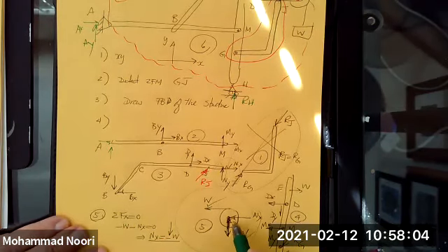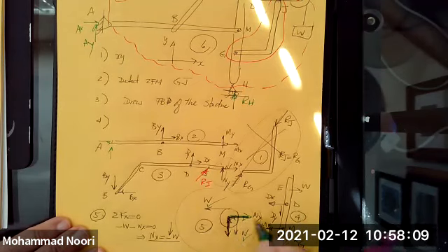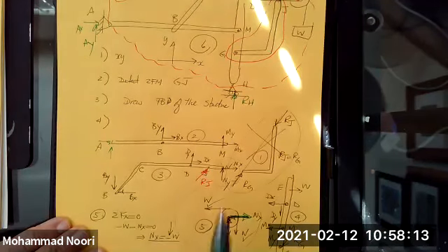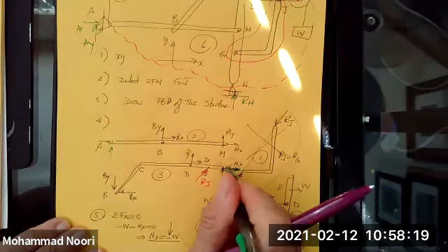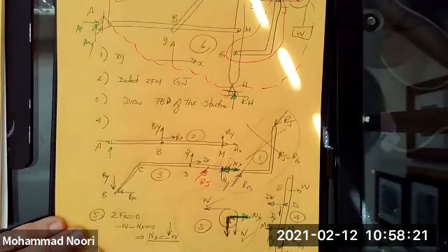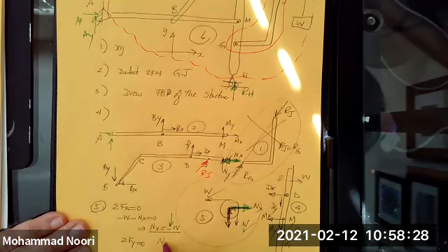As soon as I detect that, you remember, you have to make the correction, not only on that free body diagram, but on all other free body diagrams where this force appears, which is here. So I would have to make that correction. Then I use the second equation, and that will give me negative Ny minus W is equal to 0.